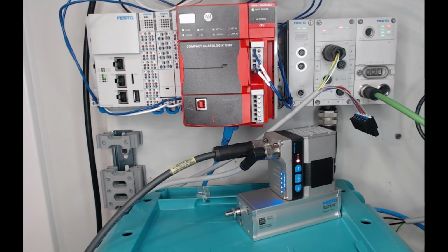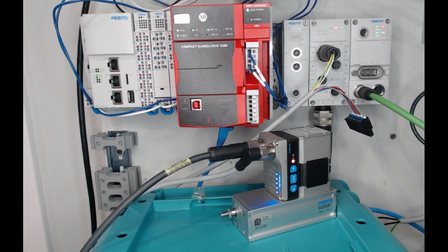So to overcome this, we have a new startup AOI which will perform this home move and also clear any recoverable errors so that when the done bit goes high, you can then move forward with any normal operation.